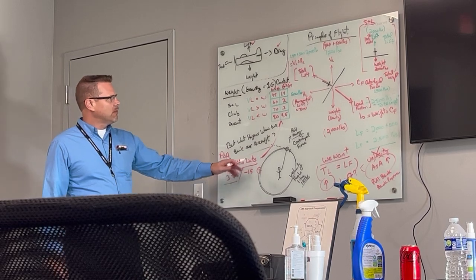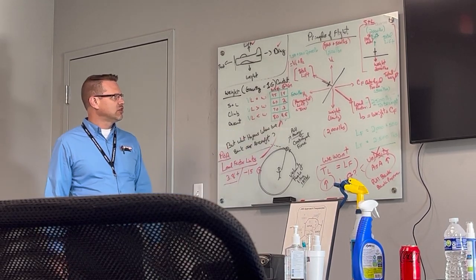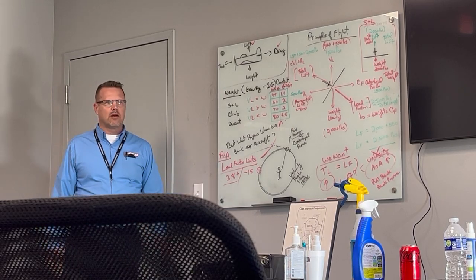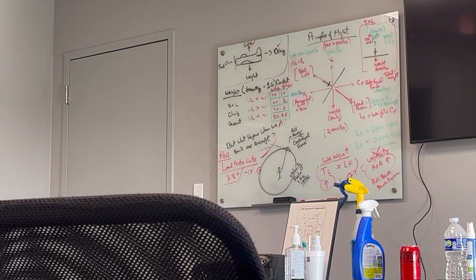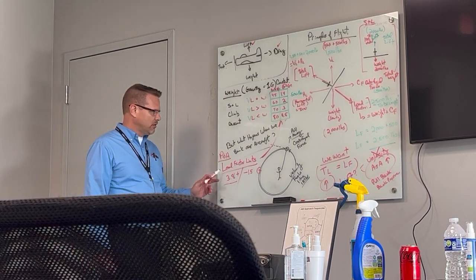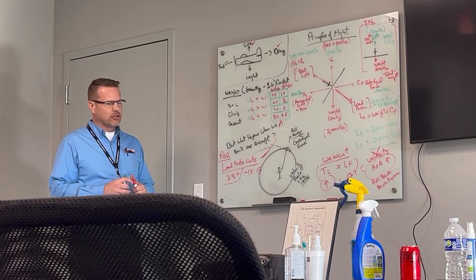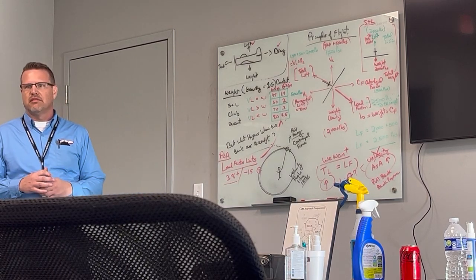So if we throw our plane into an 80-degree bank and experience a 4.5 G turn, most likely we will come out of that turn without our wings. So it's pretty important that we know this stuff. Anything that exceeds a load factor limit of the operating handbook can cause structural damage and/or actual breaking apart of the aircraft in flight.